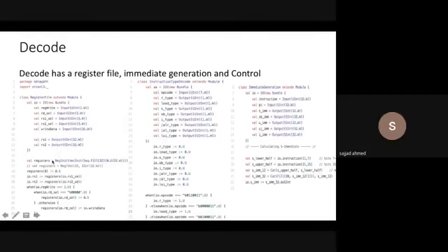Then we have the register file constructed using the same RegInit construct of Chisel. It has 32 registers, 32 bits wide, with reset value 0. Then we wired register 0 to a hardwired 0. It is an architecture constant that register 0 always contains the value 0. As you saw in memory, the register file gets addresses R1 select and R2 select and wires them to the outputs io.r1 and r2. Then we have some conditions for how the register file will be written or read, using the when construct of Chisel. When is basically a mux. You can define a mux or use a when construct; at the backend it will be the same.